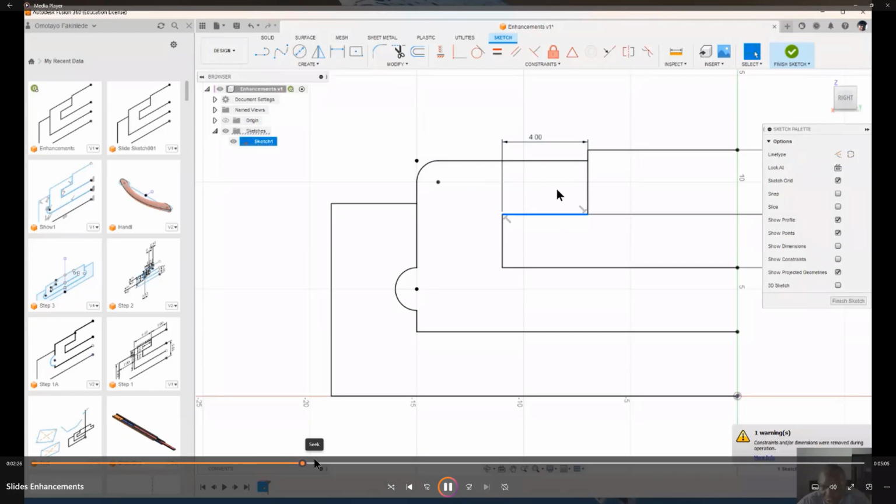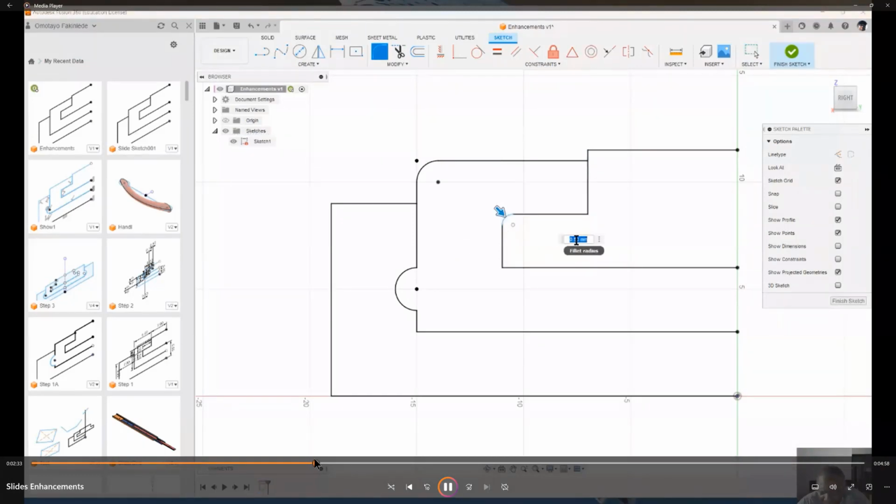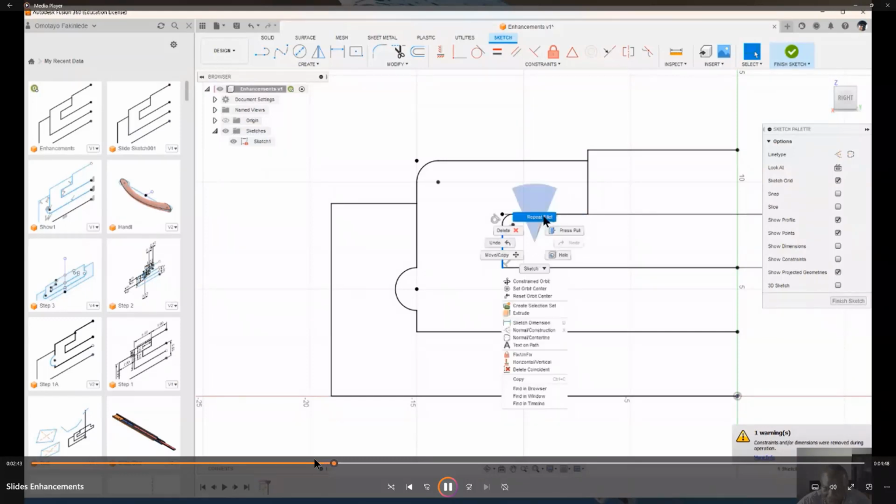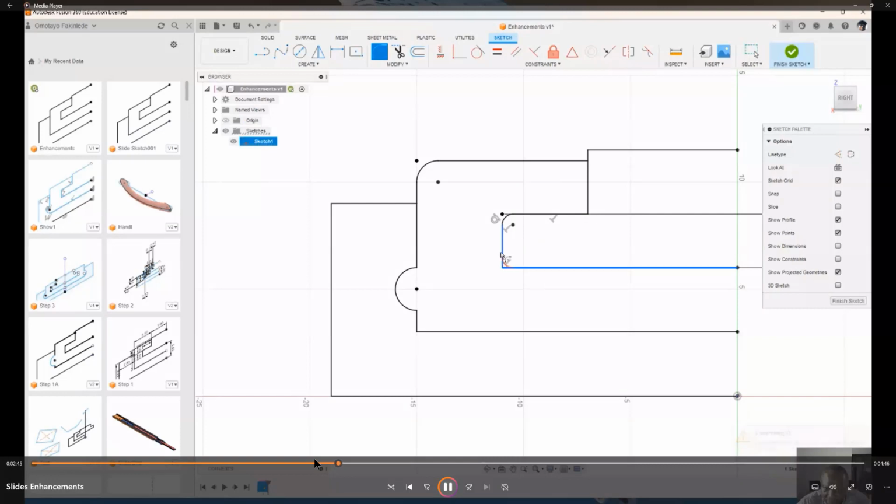The fillet tool is gone, so we use the marking tool by right clicking, repeat fillet. So it gives us this one and this one. Now it's saying 0.5. That's okay too. And then we do a fillet from here to here. It's not agreeing, so we use the marking tool, repeat fillet from here to here, 0.5. That's also good. So we have the fillets, and if we're happy with all of that, we can now do what we call an offset. So we can do an offset for 2 of the profiles.